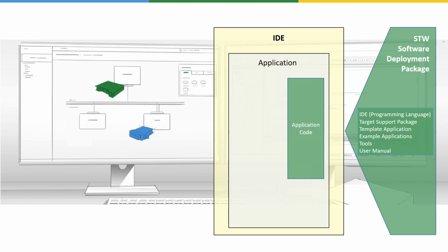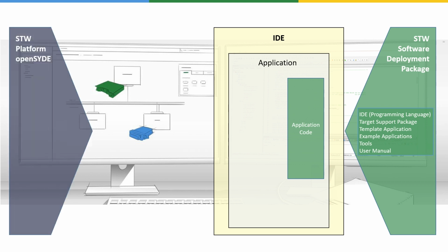During application development, you will have to program a number of BIOS functions yourself for each individual input or output, which means you will have to take the BIOS functions from the user manual and program each individual parameter required in the code of your application. For controllers such as ESX3CS, where the Hardware Configurator feature is already available, openSYDE can conveniently support you with this programming.